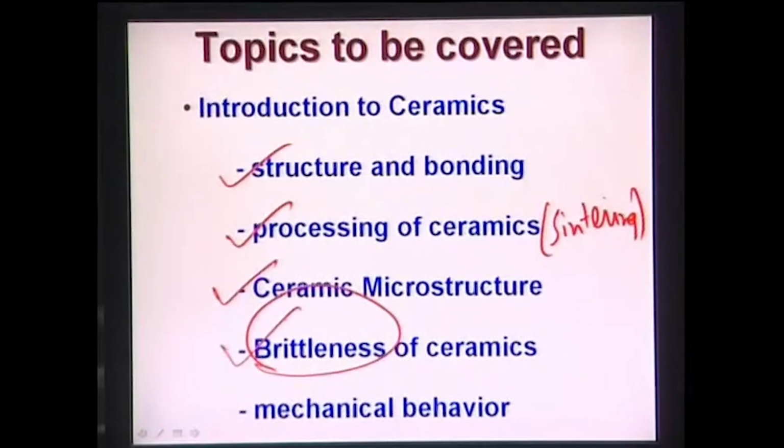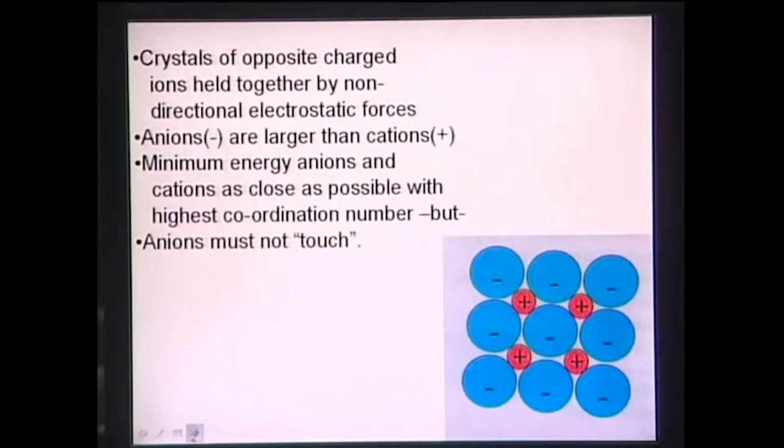And except for the fracture toughness or the toughening behavior, the general mechanical properties of ceramics like hardness and strength, how they are experimentally measured, and what the different formulas typically used to determine the mechanical properties are, also will be discussed. Now, typically ceramics are defined as a class of inorganic solids which have covalent or ionic bonding and which are used at high temperature or processed at high temperature, either of the two. In both cases, you can call that class of materials ceramic materials.